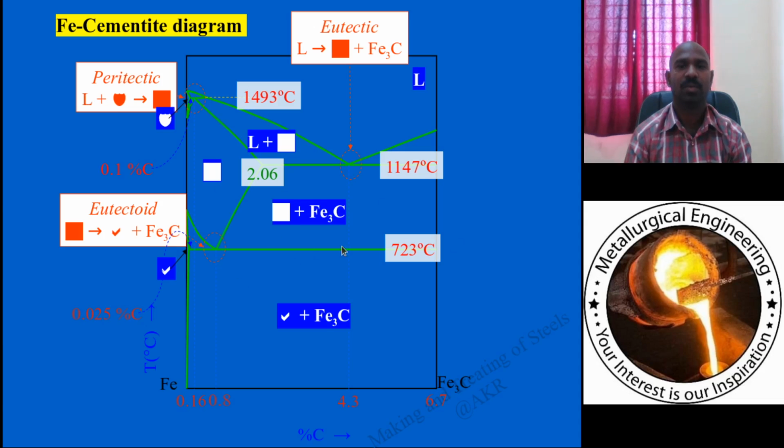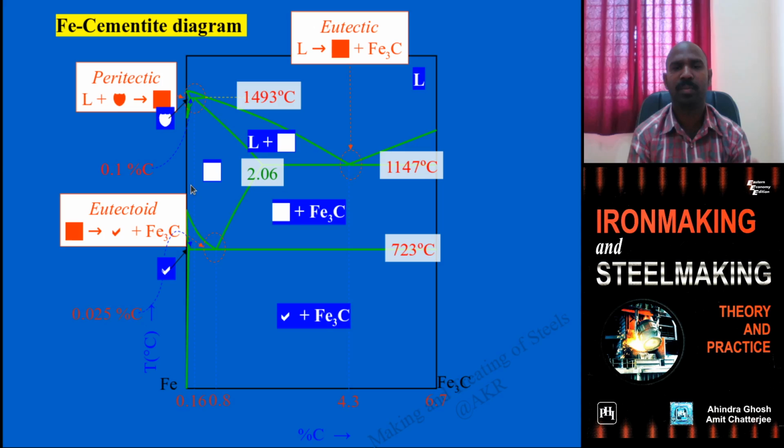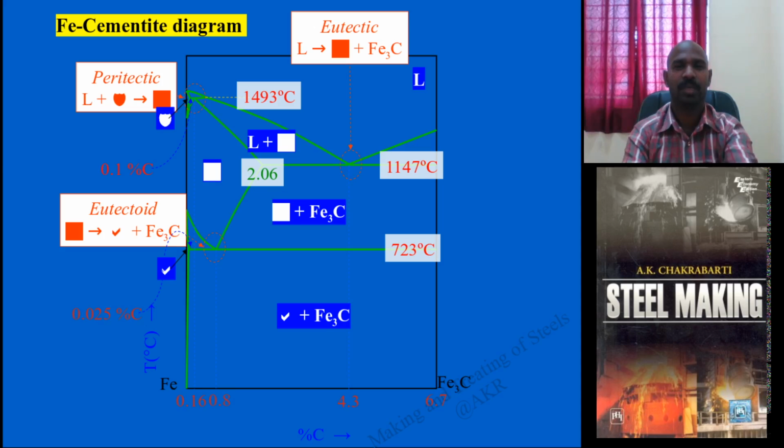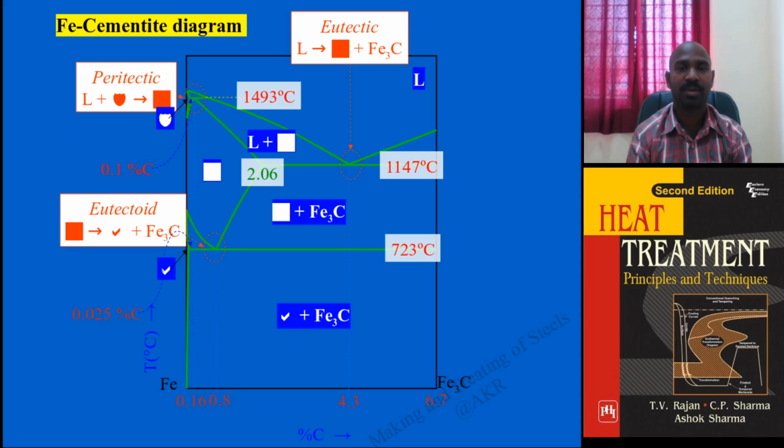If you take this particular steel, it is broadly studied that if you take eutectoid steel, above this it is entirely austenitic region. Can you convert this particular austenitic steel into various phases and microstructures with respect to hardness for various applications? It doesn't mean that steel coming from secondary steelmaking and continuous casting is suitable for all applications without further thermomechanical and heat treatment processes.